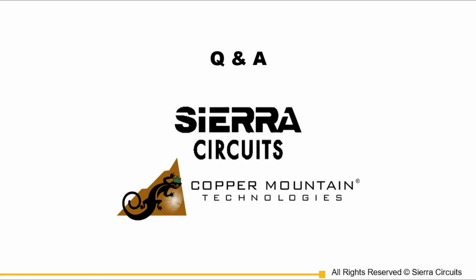I think the issue might be that the calculators generally are based on Wheeler formulas. They kind of fall apart if you go to certain extremes of mechanical dimensions. So that might need to be done in a planar EM simulation like CST or ANSYS. Right, ANSYS, yeah, you're right. But I have a feeling that people who use silicon dioxide and these kind of things have a special calculator for that. That's what I'm not able to put my finger on.